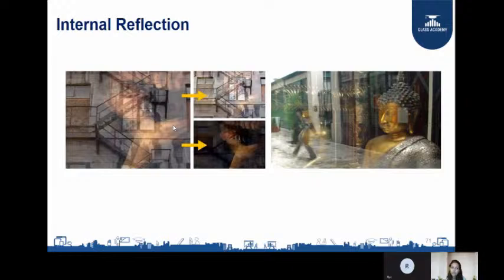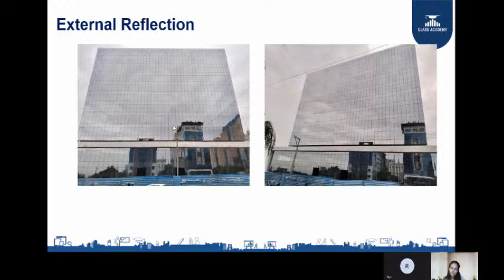So you can see here that the percentage transmission, whatever VLT you are getting through the glass, will depend on the substrate of the glass, what substrate, what tint you are using, and also on the coating, what particular coating you have used on the glass. So if I say that 35% is the VLT of my glass, what does it mean? That it will allow 35% of the light incident on the glass. Say 100 lux is incident on my glass. From that 100 lux, 35 lux will come inside. That is the definition of VLT.